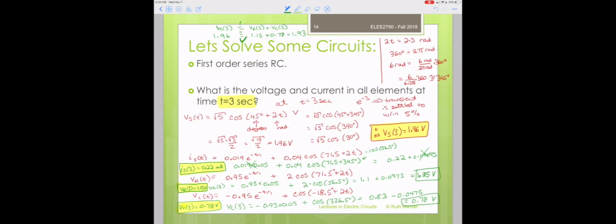So this is actually correct because we rounded a couple of things early. So we're happy because we see that Kirchhoff's voltage law works, everything is where we expect it to be, everything is pretty good, and we've been able to solve all the exact equations for the time values. We've been able to figure out the transients, the steady states, the coefficients, and even apply that to get some voltages as time moves on.